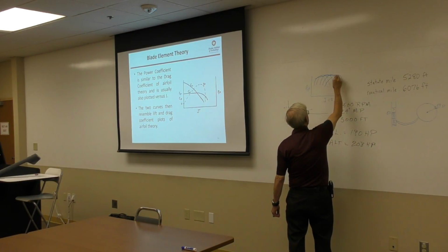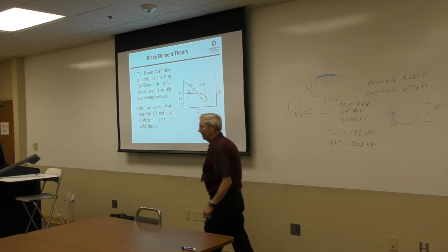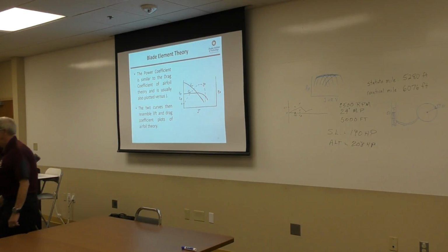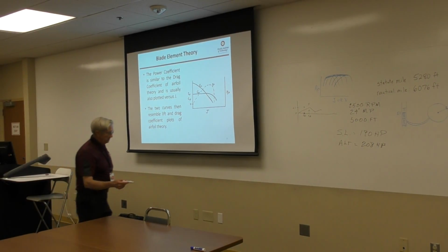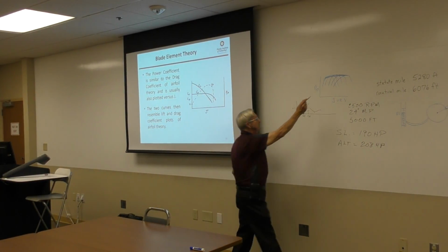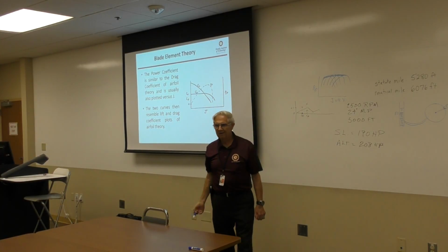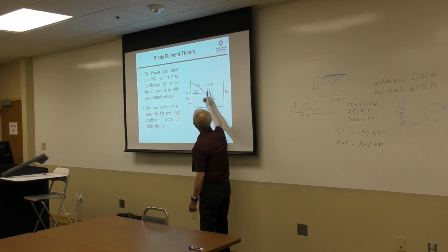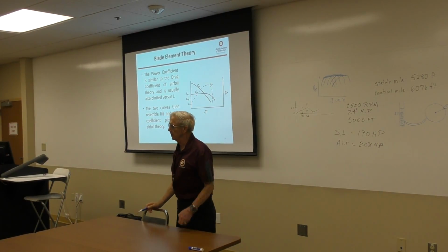The propeller is operating up here. And that's the kind of thing we have on the Cherokee 6. We have a constant speed propeller where it is operating up here on the peaks of these efficiency curves. However, a fixed pitch propeller looks like this. There's only one advance ratio where it's the most efficient.